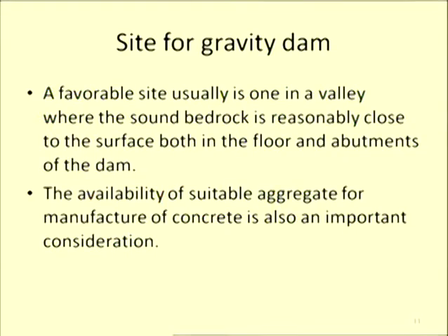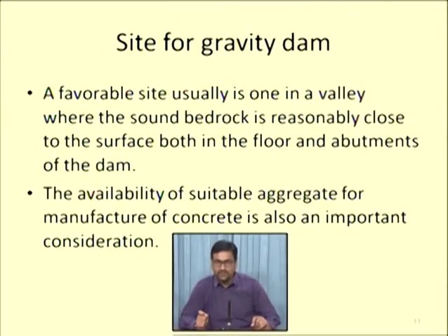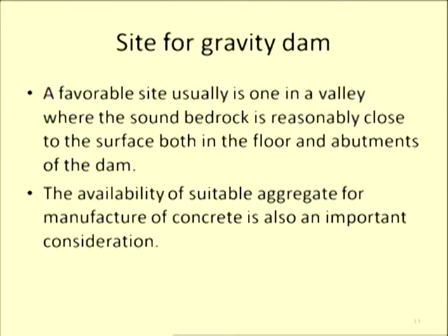So again I read it that a favorable site usually is one in a valley where the sound bedrock is reasonably close to the surface, both in the floor and abutments of the dam. The availability of suitable aggregate for manufacturing of concrete is also an important consideration.